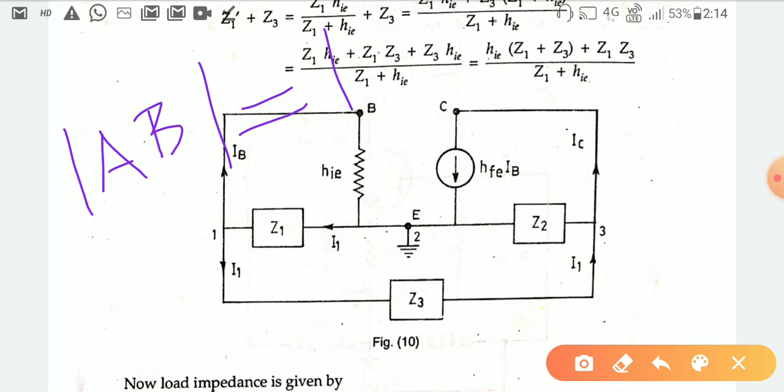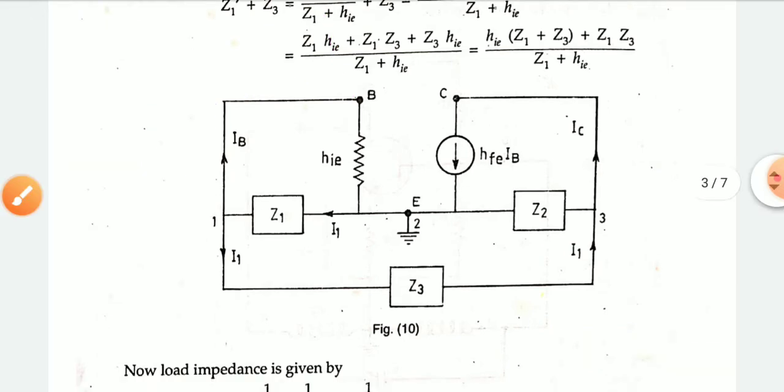So you have to identify what will be the value of the voltage at the output side, what is the voltage at the input side, and the ratio between them to get the value of A, and in the same way what portion of the voltage comes back to the input side as feedback, and on that point we can calculate the value of beta also. For this reason initially we have to take the output impedance, because if we identify the output impedance and multiply it with the current, the total voltage drop will come out. So what will this be?